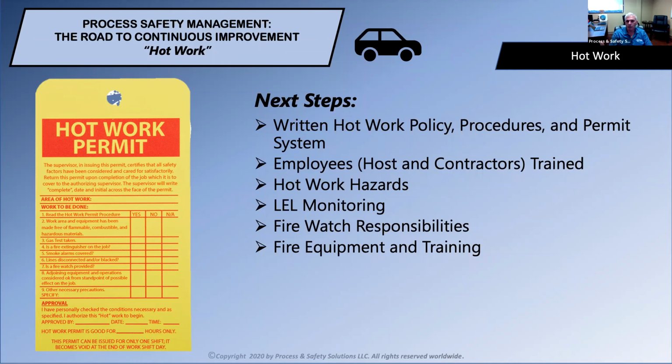Not only the fire equipment, but also the welding equipment, the hot work equipment, making sure that they understand those hazards. What is a frayed wire? What is a frayed cable? What does a hose or a torch assembly look like in good condition versus bad condition? And providing some training, including some verification of understanding in that training, so that we can ascertain whether or not they understand the training they were given as well.